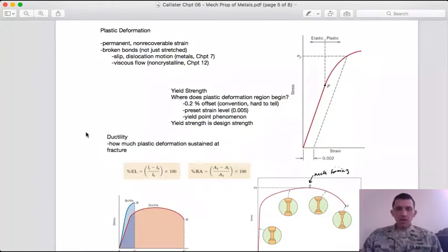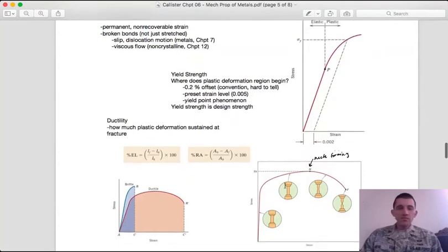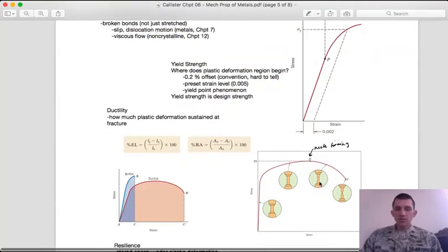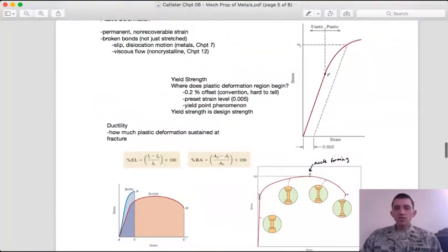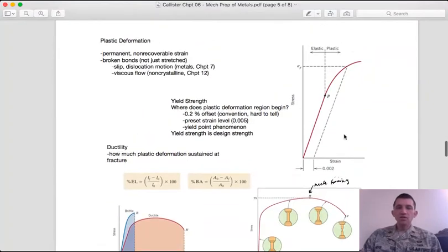or my part. But the exact transition between elastic and plastic is not always immediately apparent, even for materials like this nominal stress strain curve that I showed earlier, where there's a defined region where clearly it begins to yield. It's still difficult to say, did it happen here or here? Where in this region did it exactly happen? And so we determine the point of yield not so much by looking at where the curve changes, which can be subjective.